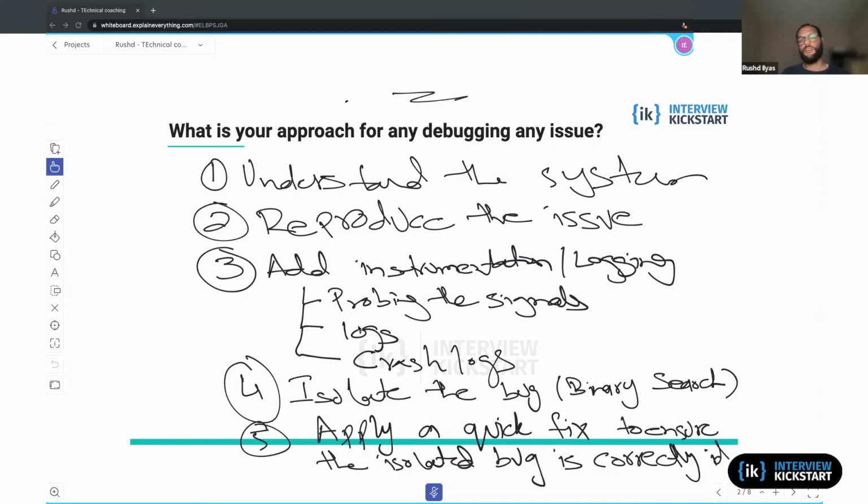I won't be able to talk specifically about airports, but I can talk in general. In general, we have an RTOS, and a lot of RTOSes give you this flexibility where, if it crashes, it goes into the memory fault handler or hard fault handler, or whichever fault handler, or an assert happens. In the assertion handler, usually they let you store information in a certain location on the flash or on the non-volatile RAM. Usually there's some space associated just with that, and then you reset.